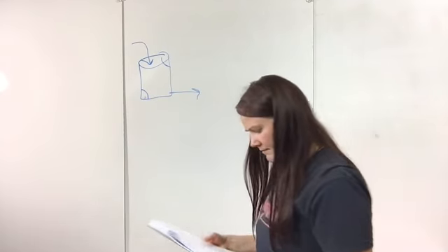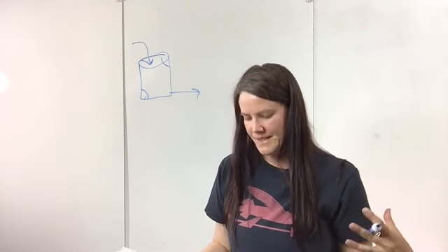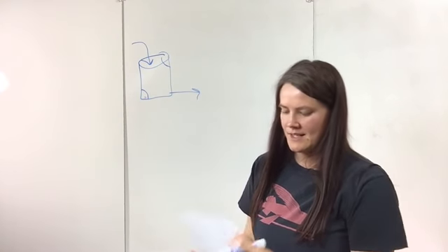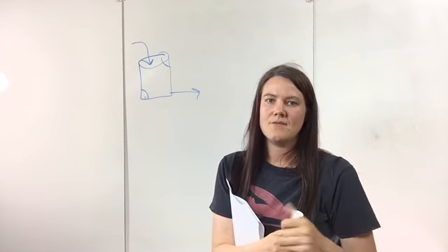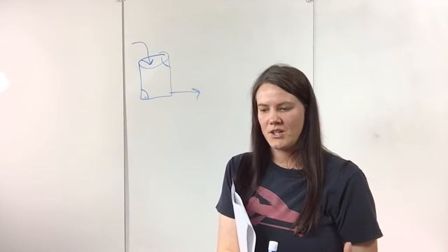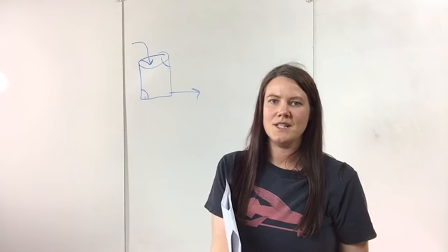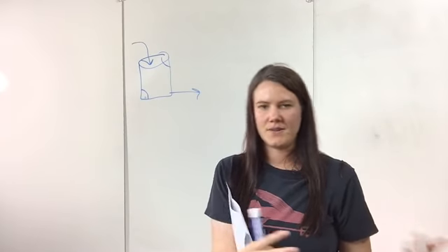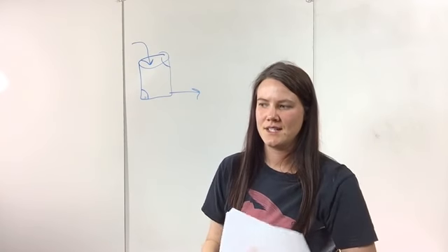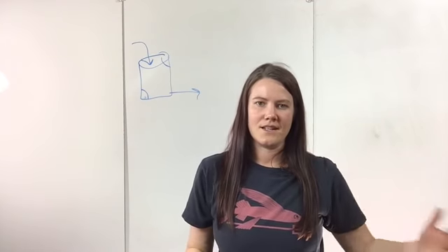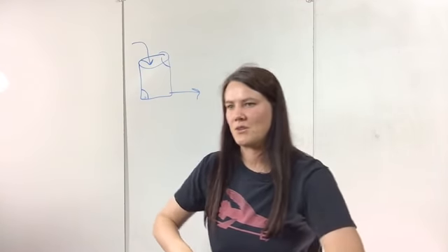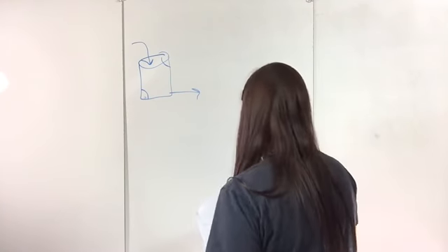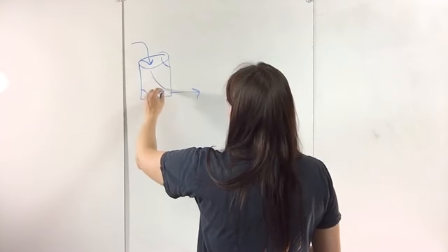So basically, it's maybe not perfectly mixed. The other thing with ideal reactors is you're assuming that every molecule spends exactly the same amount of time in the reactor, but in reality, they probably spend different amounts of time in the reactor. So some molecules flow through the reactor immediately, and others sit in the reactor for a while and don't exit immediately, like if there are some in these dead zones, and molecules flowing through the middle of this reactor might go straight through.